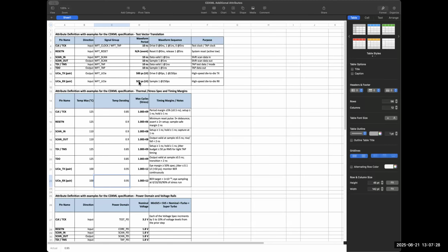And so this will be a relative section for any synchronous clock groups that you want to have. Let's say a design might have multiple scan clocks, for example, so they can alias all those clocks under this signal group so that the tool understands it has to synchronously toggle all those pins across the patterns. And that is one example. Similarly, for the reset, we want to force 0 at one period and then release, forcing the opposite value in another period. So that is another example.